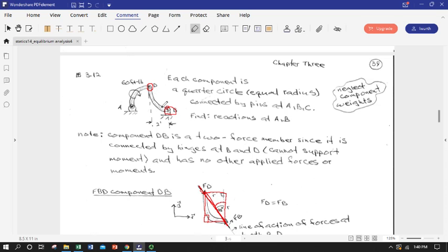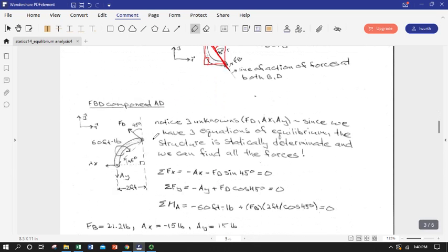because the reaction forces at point B, the support reactions, are only going to be reacting to whatever the member places on them, and the same thing up at D. So if we do an FBD of pin D, this force of member BD on the pin is going to be reacted against by this. So we now know an important piece of information.